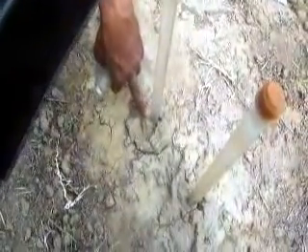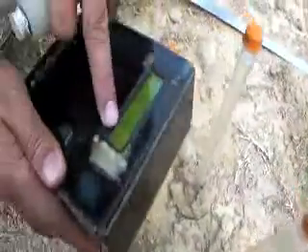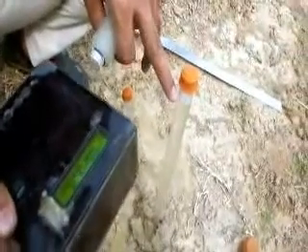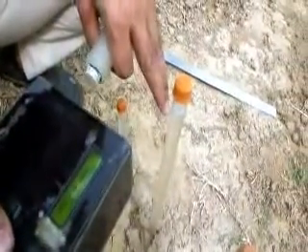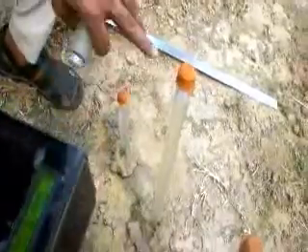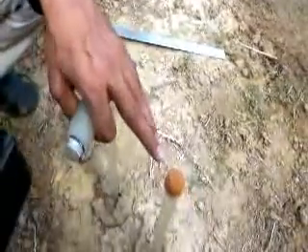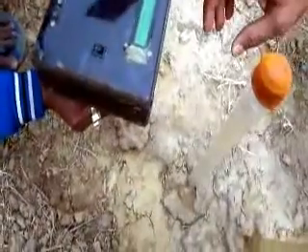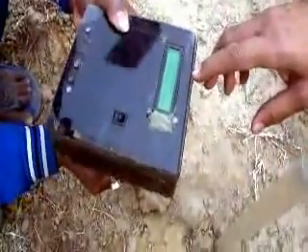So we can measure, in terms of millibar, the suction head that is created by this soil because of soil moisture content. Less soil moisture content means more suction, and with this millibar suction we can use a calibration curve to find out the soil moisture at 30, 45 and 60 centimeter depth of the soil. Now let us measure the suction head inside.